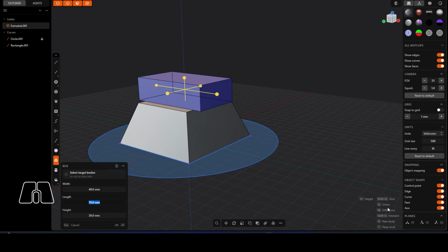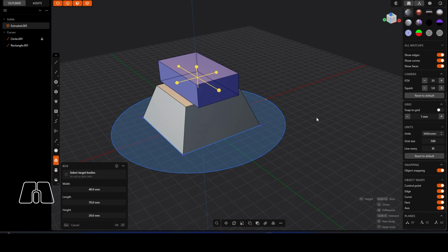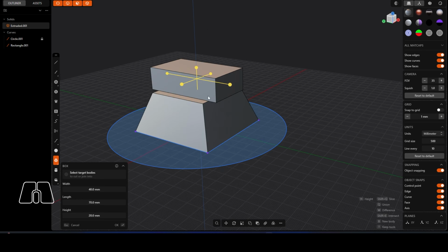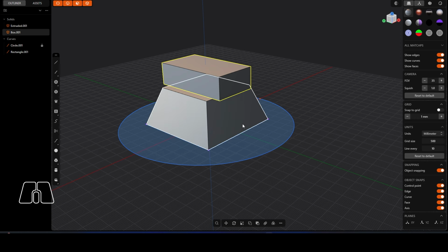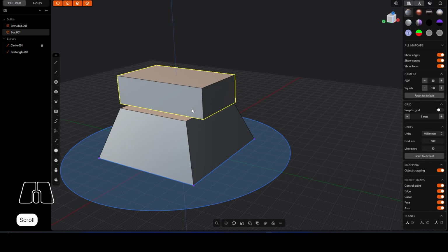And then over on the right hand side here, you've got the different things. So what we need to do, the shortcuts here, we use B to create a new body. So if we click B, no, I'm still in the thingy mode there. So there we go. So if we click B, that'll put it into a new body. So you see the coloration changes, meaning it's not going to be attached to this. So that way I've got 2 new bodies now. So that's quite handy.